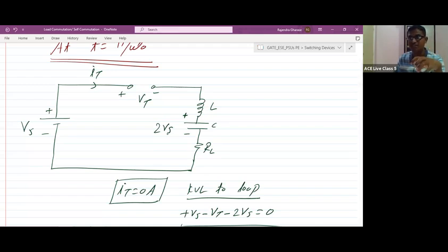So in this circuit, can we say what the circuit turn off time is? After t equal to pi by omega 0, the reverse voltage will be maintained across the thyristor for all the remaining time, so the circuit turn off time will be infinite, unless we connect another circuit here for discharging the capacitor. Till that instant the capacitor will hold the same voltage, 2 Vs, because the discharging path is not available. This is the class of load commutation, or self commutation, for low value of RL. Is this clear?